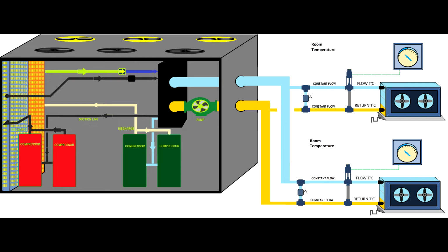And if the cooling agent on the flow side has a very high temperature, then I don't have to look at this three-way valve or the actuator, because it's not a flow problem, it is a temperature problem, and the temperature is governed by the cooling capacity, and the cooling capacity of the cooling agent is directly connected to this chiller.